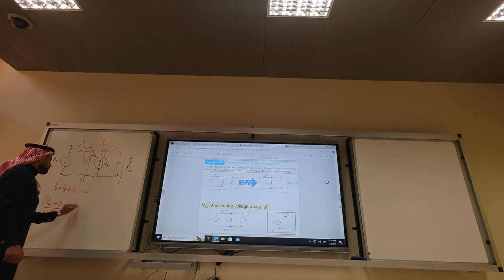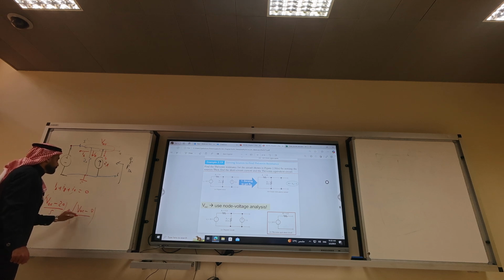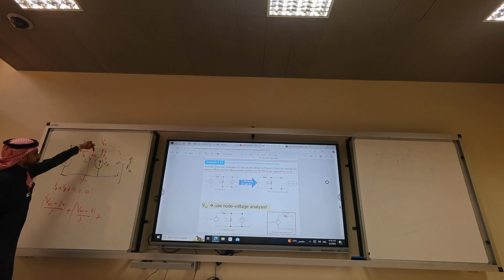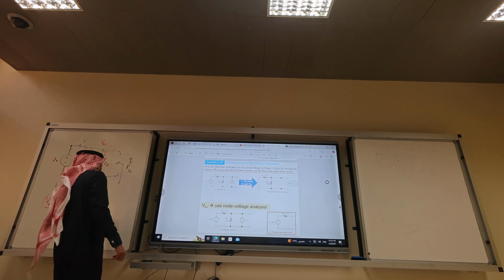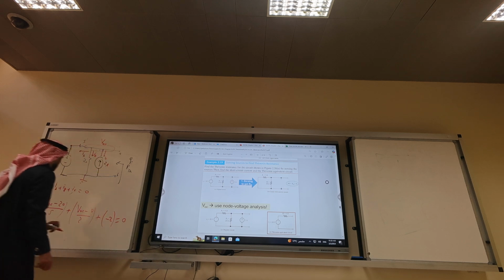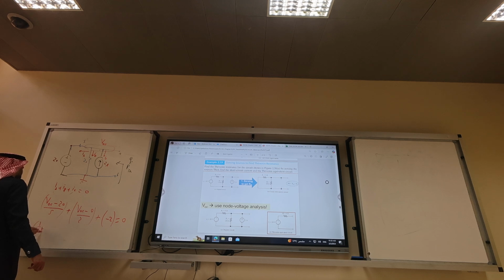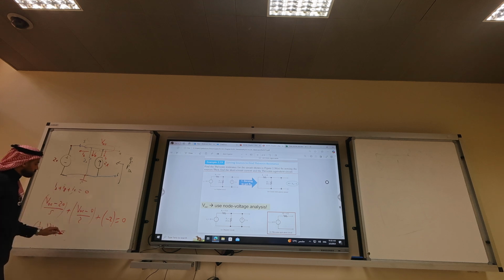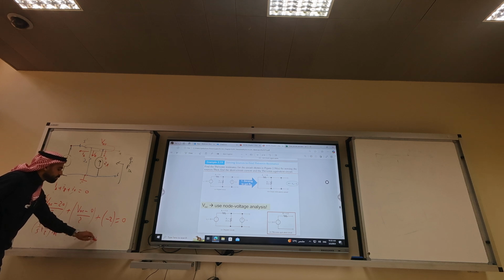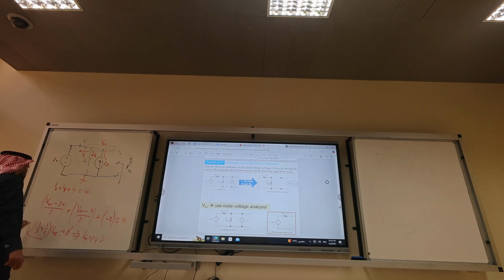VOC minus 0 over 20. What is IC? Minus 2. So solving, it's 1 over 5 plus 1 over 20 VOC equals 20 over 5, which is 4, minus 4 minus 2 is minus 6. Put it there, it will be 6. So if you solve it, V open circuit is 24 volts. Basically, this is 1 over 4.